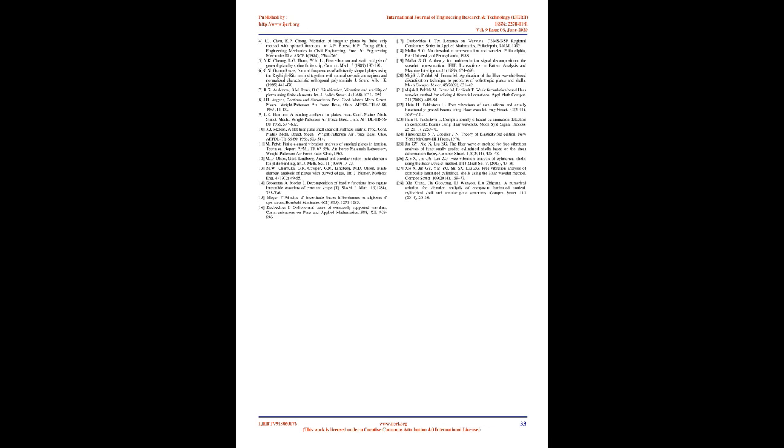Tables 2 to 5 show the natural frequencies of the plates for different thicknesses under several boundary conditions using the presented method. Fig 1 shows the natural frequency change of the plate with increasing aspect ratio under several boundary conditions. As shown in Fig 1, the natural frequencies decrease as Ly/Lx increases. In particular, it can be seen that the natural frequencies decrease rapidly until Ly/Lx equals 1, then decrease gradually. Lastly, Fig 2 shows the change in natural frequency of a plate with a completely clamped boundary with increasing thickness h. It can be clearly seen from the figure that as the thickness h of the plate increases, the natural frequency also increases.